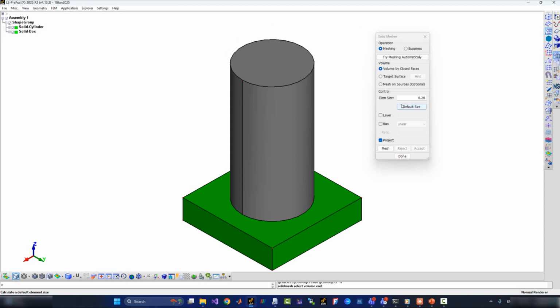So what I'm going to do first of all is give an element size. I'm going to select an element size of 1/2 inch. So this should give us what? We have a height of 12 inches for the cylinder. We should be having a total of 24 elements along the height. This will also be the approximate size inside the cross-sectional plane. But of course, the cross-section geometry is a circle, so we don't have nicely shaped, square or quadrilateral elements, as we will see.